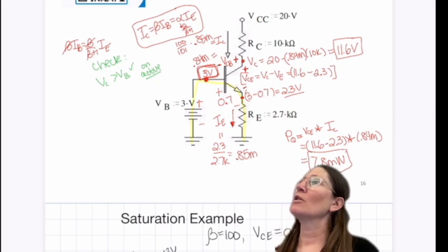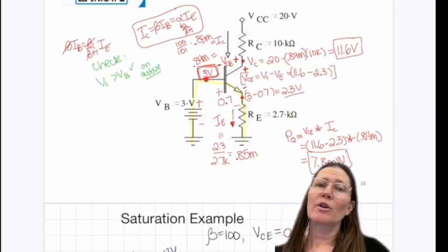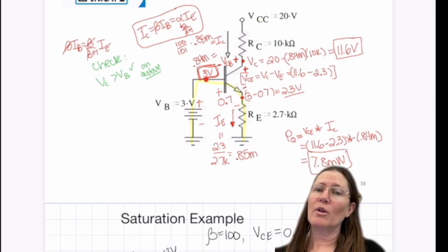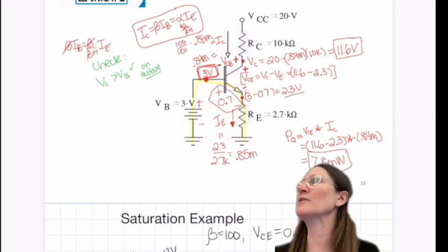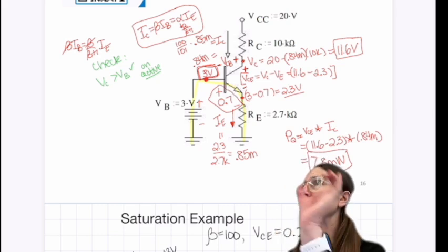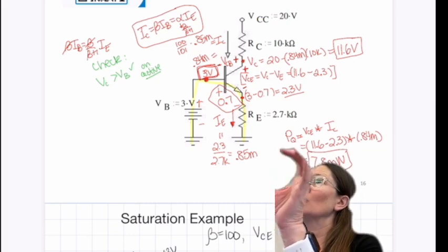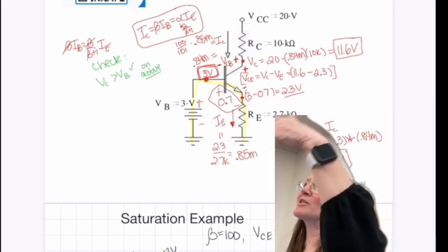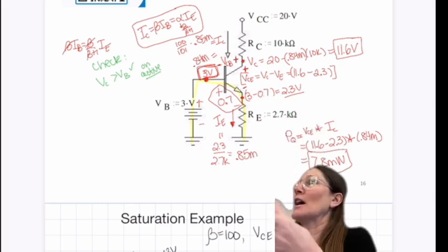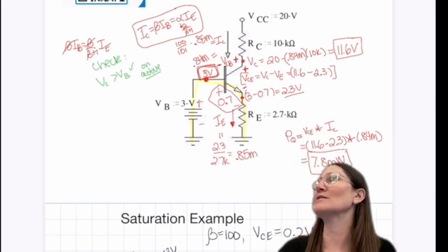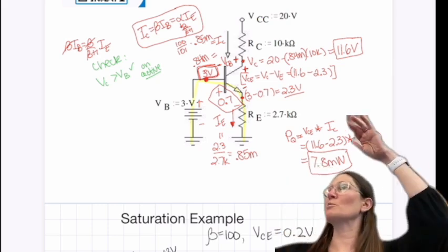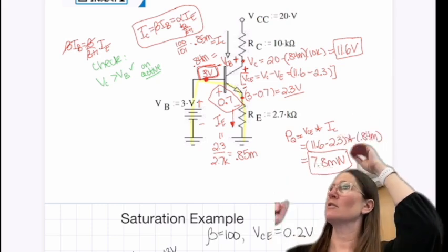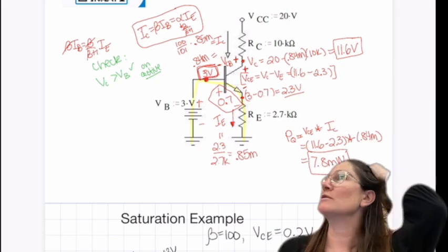It's not a known voltage internally. Is there no voltage drop across the lower line, like when you go from the 3 volts and then you did this subtracting 0.7? So we know that this is fixed at 0.7 if it's on because it's acting like a normal diode. Okay, so that's why we can go through that route, because it has a 0.7 volt drop to it. So that's why we take that loop. So it's not zero between there. It's not zero between any of the junctions. You just don't know what that voltage is.